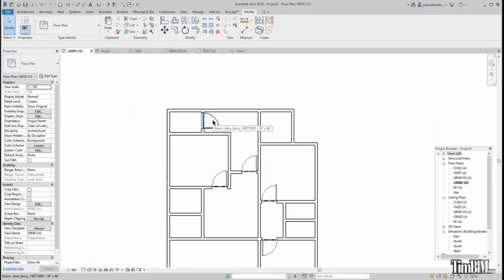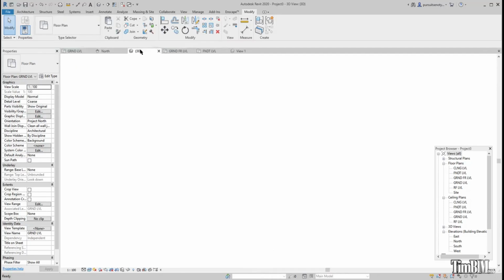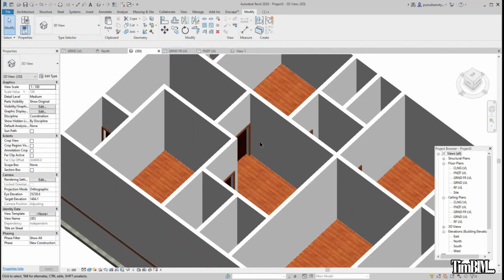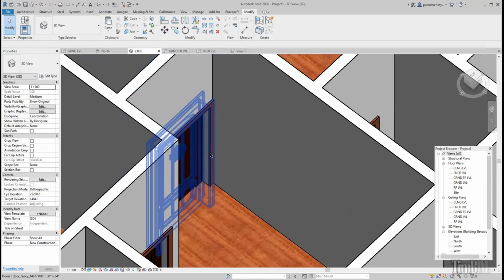In this case, if you see all these doors that we draw, they are on ground level. This is not where we are supposed to be drawing the doors. They are being drawn at ground level. So if you check all the doors, they are being placed at ground level, and you see that it penetrates, it goes down to the ground level.